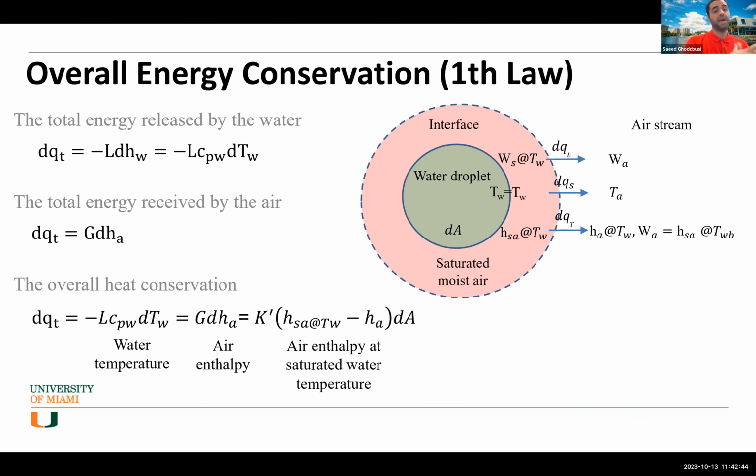But another thing is that we have an overall energy conservation law based on the first thermodynamic law. The total energy released by the water can be expressed based on the enthalpy difference and also temperature difference, and the total energy received by the air based on the enthalpy difference. And we can have the overall heat conservation law for the water side, for the air side, and for the air enthalpy at the saturated water temperature that we have, right?